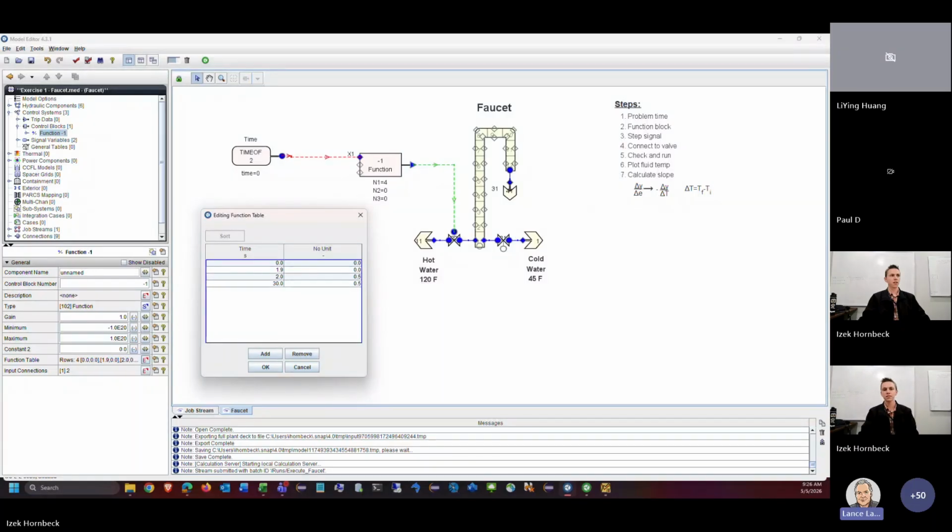And the reason it's a negative in this case is because the definition of error we're going to use is our target value minus the temperature signal. So that's why we're swapping the sign of this slope because of our choice of error.